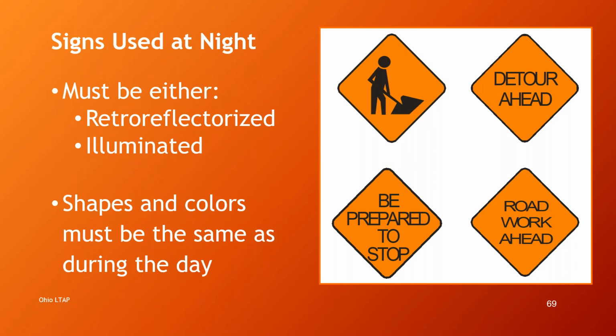How about signs used at night? Sometimes we have to do our roadway maintenance activities at night. You'll see a lot of ODOT projects, especially on our really busy roads and interstates around cities especially. We like to do a lot of our work at nighttime because there's less traffic and less inconvenience to people. But the signs we use at night, they're basically the same signs we use during the day in the typical applications, but they need to be retroreflectorized or illuminated.